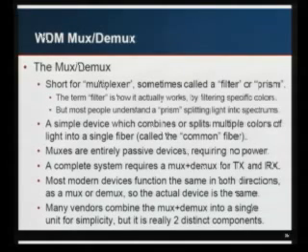It filters specific colors of light and sends that specific color of light out a port or accepts it from a port. It's not really a prism, but people understand the concept of a prism splitting light, and so sometimes people call it that. It's a very simple device. It combines or splits multiple colors of light onto a single fiber, which is called the common fiber. They're entirely passive devices. They require no power.